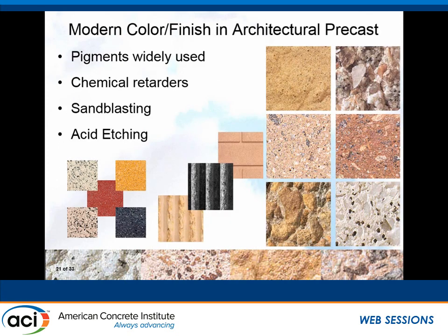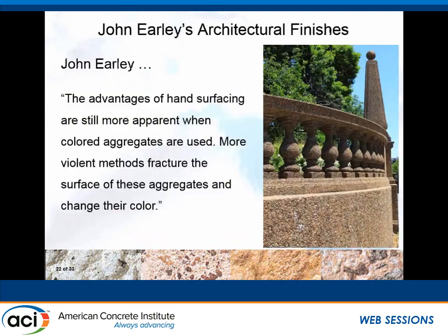We do use a lot of pigments now. We'll use chemical retarders on our forms to get that face instead of people with wire brushes typically. We can use sandblasting. We can use acid etching. And all of those different things will give you a different look.